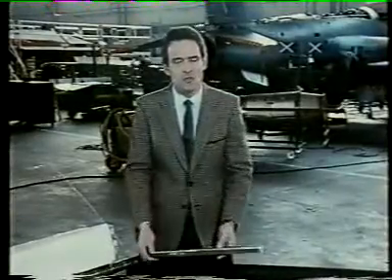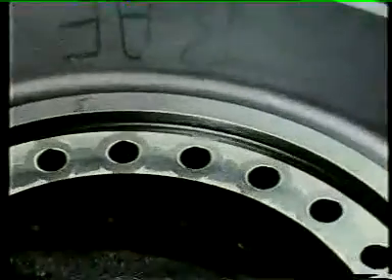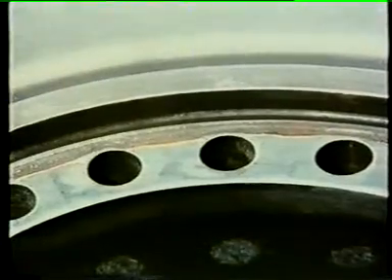Fretting corrosion is due to small movements between two load-bearing surfaces. These break down the protective treatment, leading to corrosion, and the corrosion products then act as an abrasive. Microbiological corrosion can occur in fuel tanks, although it's normally inhibited by the use of a fuel additive and by the use of chromate bags in the fuel tank sump. Galley and toilet areas may also suffer from this type of corrosion. It's caused by the growth of fungi or bacteria.